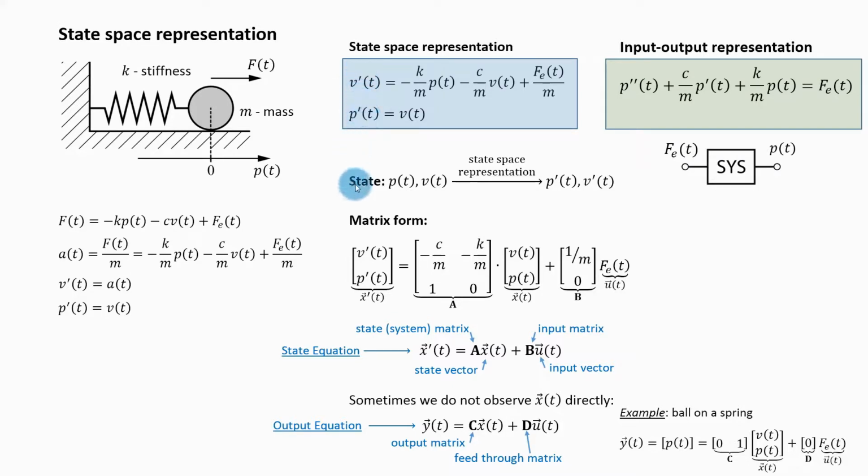So using the state space representation, you can take the state of your system, and from this state you can compute how the state of the system will change. And from this you can compute the behavior of your system just as you are able to do from the input-output representation. Now, why would you bother to use this description when you already know how to use the other description? Well, there are many methods for estimation and control that are designed to work with the state space representation of systems and are not directly applicable to the input-output relationship.